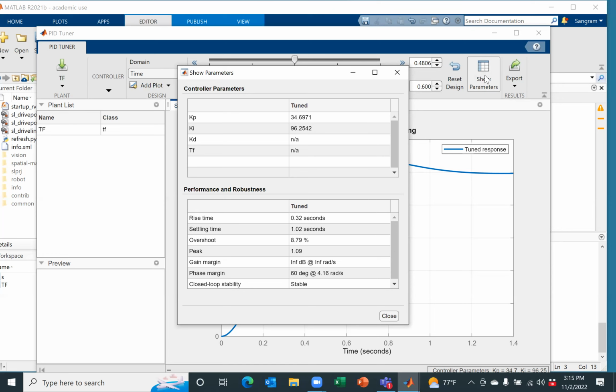The system would become unstable as soon as the eigenvalues cross the imaginary axis. I spent a lot of time talking about it, so I want you to understand. This is the S plane, wherein you have eigenvalues. Eigenvalues have a real part and an imaginary part, alpha plus beta i. This is the imaginary axis and this is the real axis.